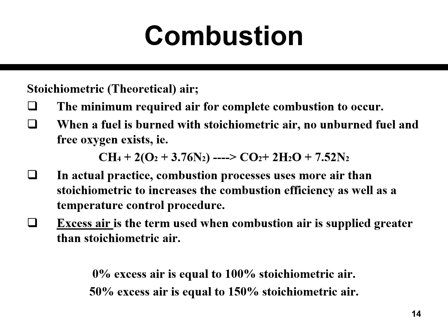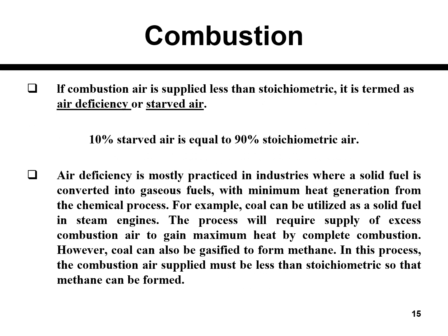When air is supplied greater than stoichiometric air, we call it excess air. 0% excess air is equal to 100% of the stoichiometric air, and 50% excess air means about 150% of the stoichiometric air. Another term is air starving or air deficiency. When the air supplied to combustion is less than the stoichiometric condition, it is known as air deficiency or starved air. 10% starved air is equal to 90% of the stoichiometric air. Air deficiency is commonly practiced in industry when converting into gas fuel.